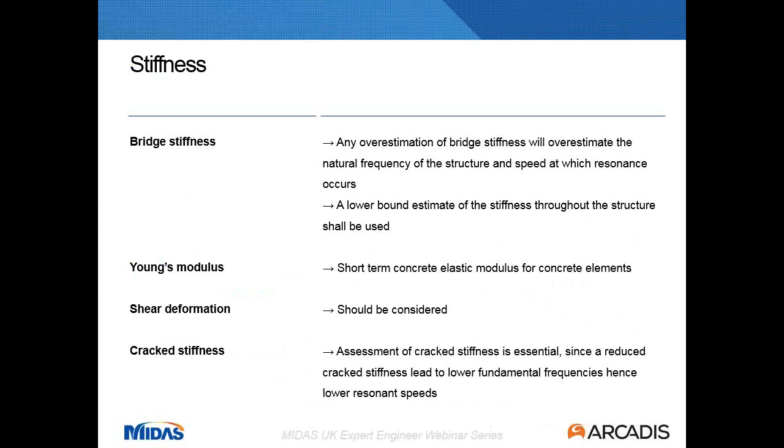Things like shear deformation, you have to make sure that you're considering shear deformation if you're using beam elements. And if you're using concrete structures that you allow to crack by design, like a composite structure where you expect the top slab to crack near the supports, you need to model the cracked properties in your dynamic model. You cannot use gross properties, because then you will underestimate the resonance effects.